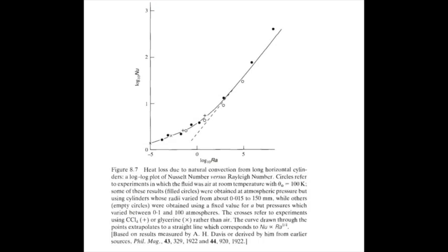Here we see a log-log plot of the Nusselt number versus the Rayleigh number. As we can see, as the Nusselt number and Rayleigh number get larger, they form a linear relationship. However, keep in mind that this is on a log-log scale. Therefore, we may be reasonably confident in our evaluation of the Nusselt number as a function of the Rayleigh number and the Prandtl number. Therefore, our dimensionless numbers and Boussinesq equations are most likely correct as well.